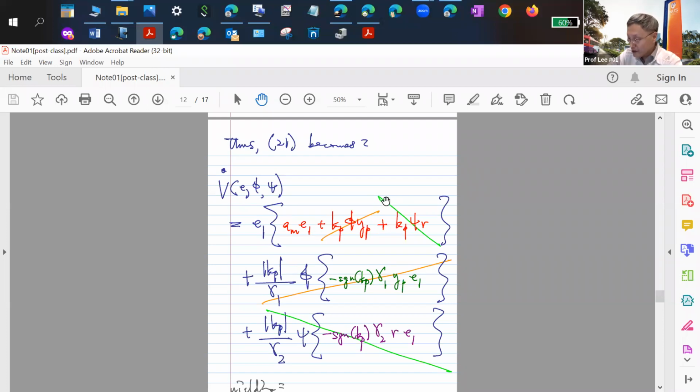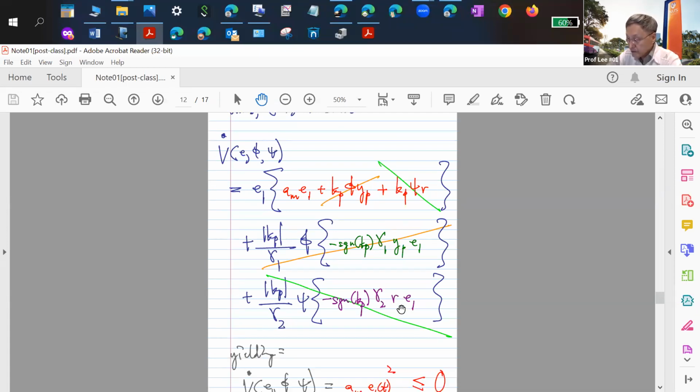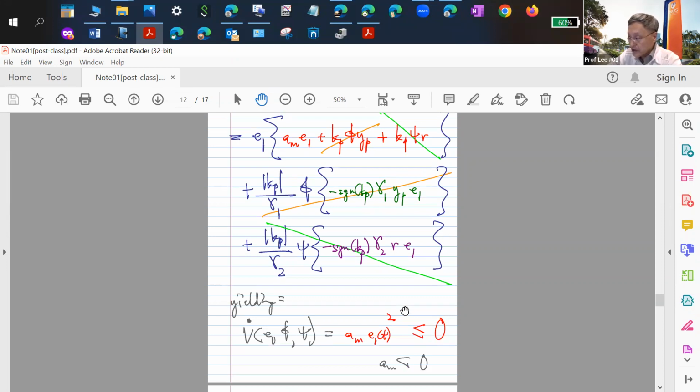Reduced order observer, this was the basis of the design. You basically choose your design equations so that you are able to handle the things that come up. So this is K dot. This is how we design it, and you can also see the same kind of thing when you multiply it out. This exactly equals this second term, cancels it out, leaving us with only the first term. So that was why we designed it that way.